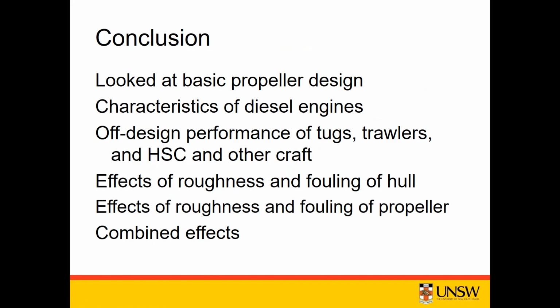If you've got reciprocating steam engines, which we actually did one of when we did the restoration of the steam yacht Ina back in the mid-1980s, we had a new reciprocating steam engine in her, and we fitted a Gawn series propeller to her, and she achieved the speed on trials.